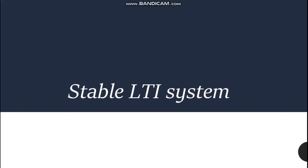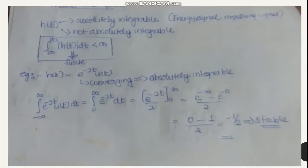Now coming to stable LTI systems. Consider that if our h(t) is absolutely integrable, we can say the system is a stable LTI system. So in a stable LTI system, our h(t) should be absolutely integrable. If that is not absolutely integrable, it means that this is an unstable system.